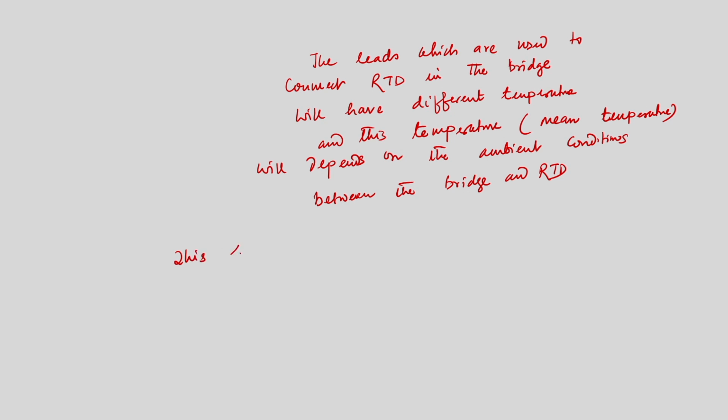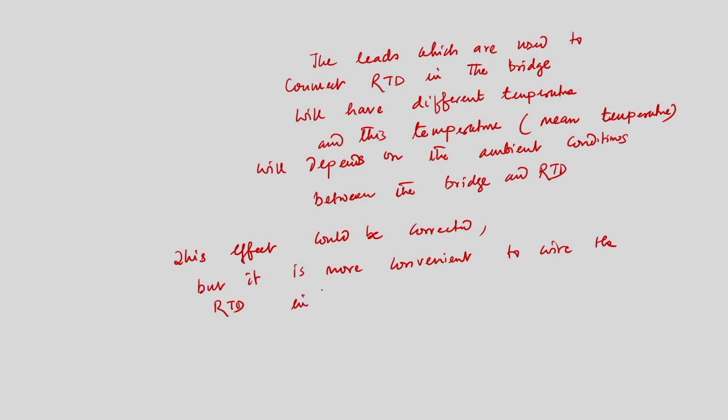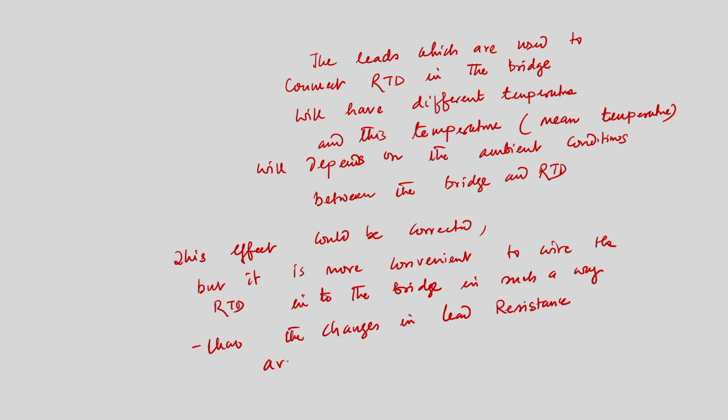This effect could be corrected, but it is more convenient to wire the RTD into the bridge in such a way that the changes in lead resistance are self compensating.